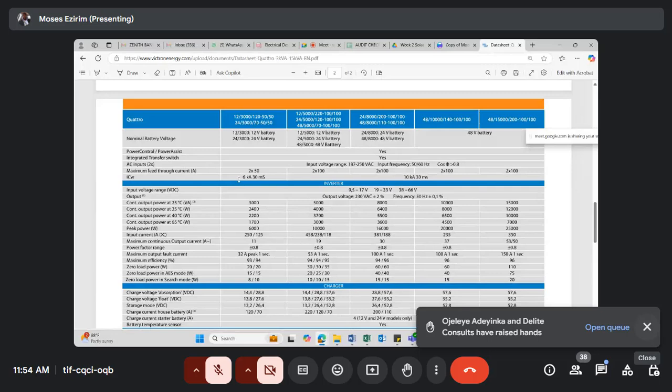So this is how you'll be able to determine the energy of your PV, to know if it will be able to supply the load of 10 kilowatt hours and be charging the battery at the same time during the day. Once you can do this, then you can size your PV as a result of that. You understand? So now forget formula. I just have to put the formula, this is introduction. But by the time you are a professional in design, you forget formula. You design based on the principle of what you want.